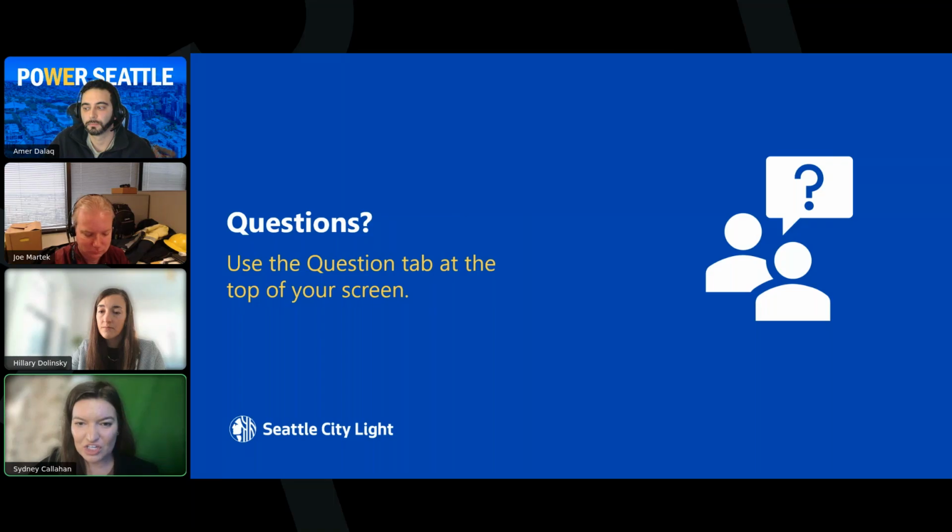Another question, do we need a knife style disconnect switch if we are installing batteries with built-in inverters if we're not tying in any generation into those batteries? Can we use a breaker disconnect or an e-stop instead of the knife style switch? A knife style disconnect switch would still be required.